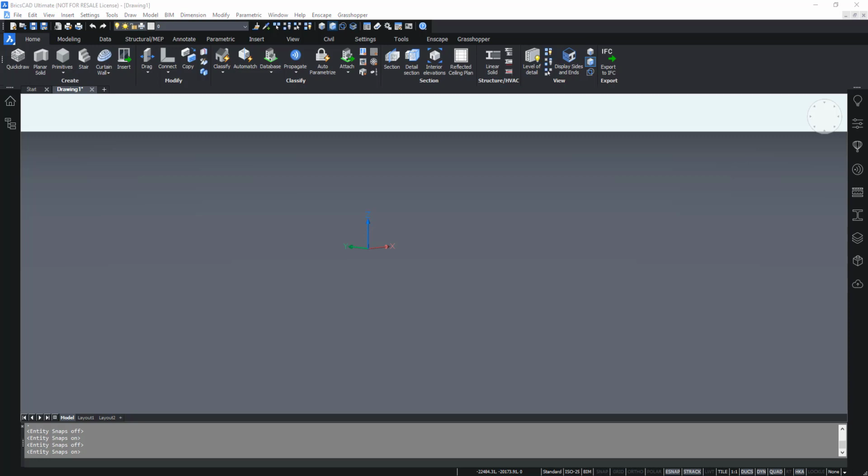Now there are a couple of other configurations that we're just going to type at the command line. The first one is DM extrude mode. And notice as I start to type that I'm presented with some options that might match what I'm typing. Once I've got those options, I can use my scroll keys on my keyboard and go ahead and select the item and just hit enter. So for the DM extrude mode, we want that to be set to 3. So if it doesn't say 3, just type in 3 and hit enter. Now this setting controls how entities are extruded, and 3 is the default setting for BIM. And that basically determines whether a separate solid is created and or subtracted from the intersection solids.